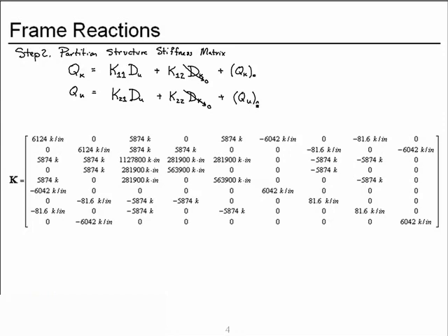And then our fixed end forces at the constrained degrees of freedom. So even though it has a subscript u, we know what these are. We will calculate them ahead of time. So I need this chunk and this chunk. Both of them refer to the unconstrained degrees of freedom. And let's number all of our degrees of freedom on this matrix. They are in increasing order. And the rows the same way.